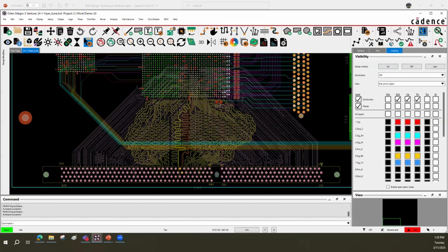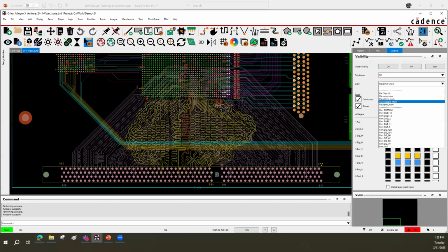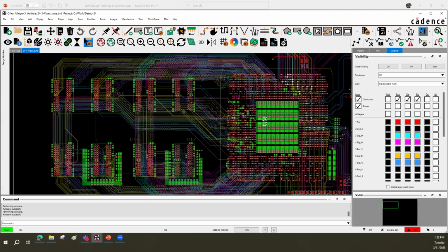Now let's go ahead and talk about on-board design. So I have some on-board memory. Here's my processor and my memory chips. Here's the first group, and here's my second group here. So we've got a routing process that we're going around into, kind of like an I2C type routing as we go ahead and route these in there. Again, placement is important. This type of memory chip, it's kind of hard to put them back to back, meaning a front and back side assembly, because of them stacking right on top of each other on there.